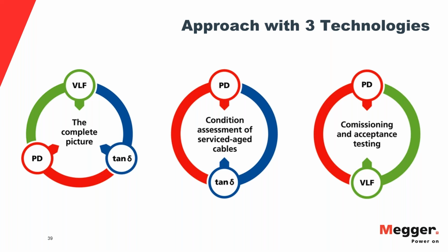All right, next question. I want to make sure I understand correctly. We calculate test voltage at 3 times the operating voltage, not the cable rating listed on the cable? Okay, this is a very interesting question because it's also unfortunately convoluted because IEEE went rogue with this.